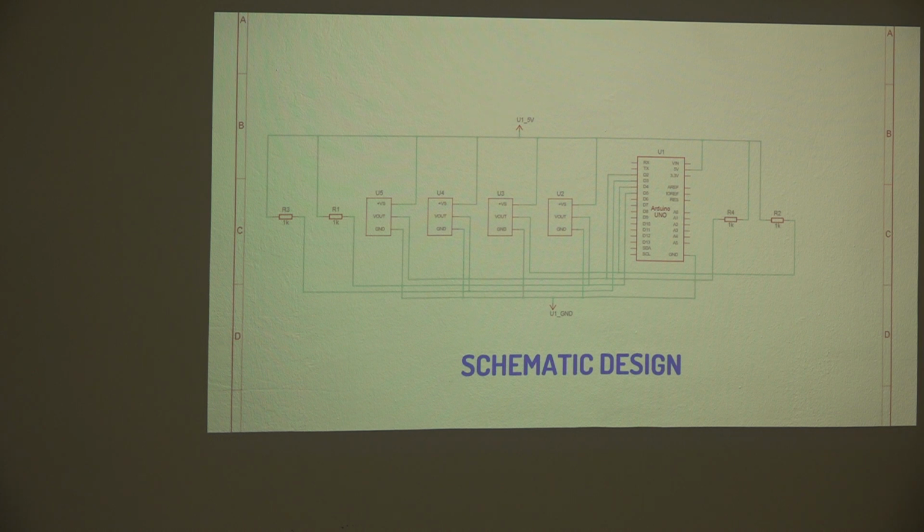Now we start to look at how we would set up our measurement instrument, since we weren't able to use the one set up by previous students. Some of the components we used were Arduino boards, resistors, relative humidity sensors, and temperature humidity sensors. Outside of this schematic, we also made use of an energy power consumption meter, and with this we would be able to test whether the different coatings on the pipe would affect the system's energy consumption. This would then affect the overall cost of running the air conditioning system.